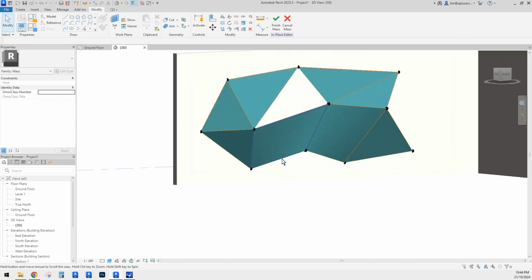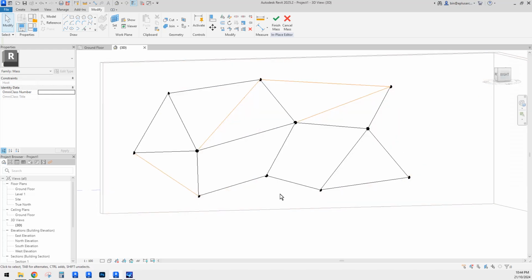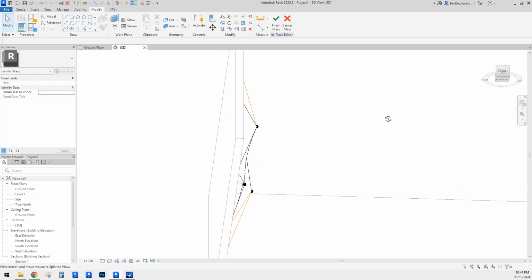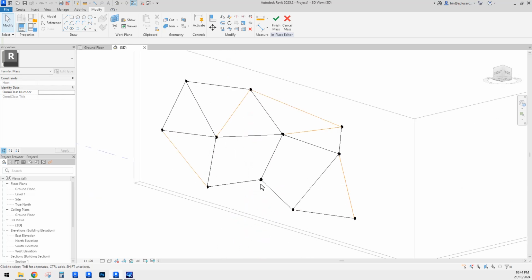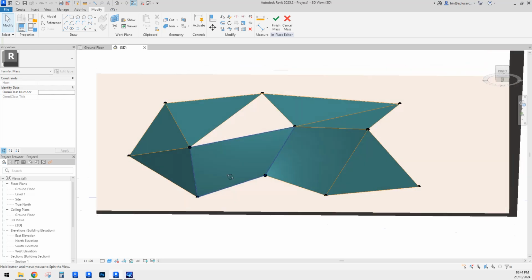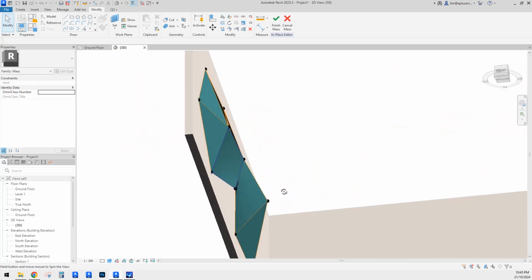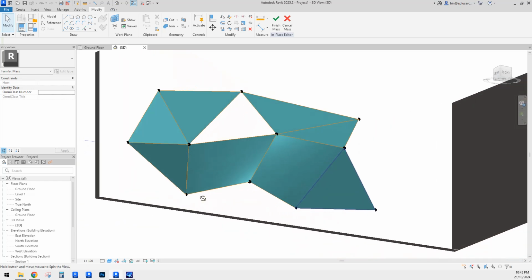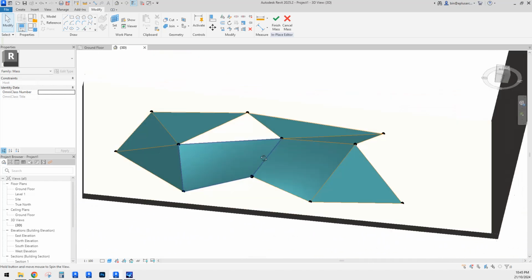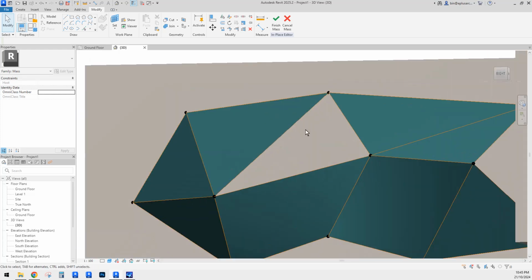See, that's a curve. Also, if it's on the hidden line, HL, you probably can't really see it, it's very hard to say. But if you use shade, SD, sometimes it helps a little bit, so you can see the shading, the color change, so you can tell it's a curved shape, right?